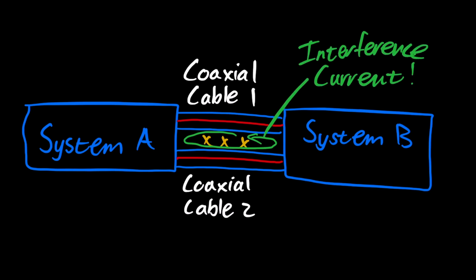This illustrates one way a common mode current may be induced on the cables within an electronic installation. Should either cable 1 or cable 2 have a poor transfer impedance, then the proper operation of system A or system B may be disturbed.